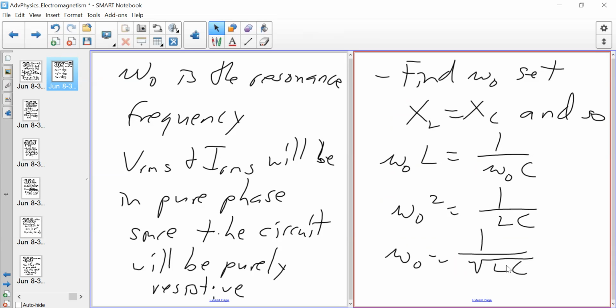So we're familiar with this in LC circuits in a non-oscillating case, and the same exists in an oscillating one. We have to force the oscillation by switching the circuit on and off. But here, this is pure oscillation from an AC voltage source. So we get this omega naught again. This is basically the resonant frequency based on these particular values of L and C.